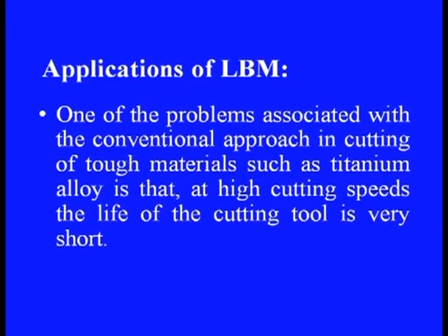One of the problems associated with the conventional approach in cutting of tough materials such as titanium alloy is that at high cutting speeds the life of the cutting tool is very short. As the titanium alloys are used extensively in the aerospace industry, there is a tremendous interest and curiosity for developing this technique, especially for enabling higher cutting rates. Nowadays, laser is also finding applications in regenerative machining or rapid prototyping, as in processes like stereolithography, selective laser sintering, SLS, etc.